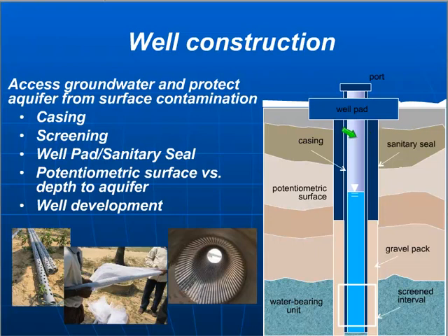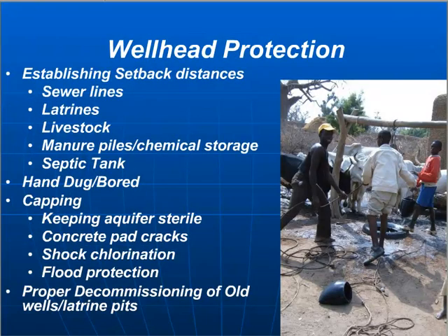And then one last slide on this borehole. There is a design that goes along with the well. Sometimes chapters say, oh no, we're going to install a well and we're using this driller, and that's all the information that's provided. But there is an actual design that you need where you specify the casing, the type of screen, the screening interval, specify that there'll be some sort of well pad, or what the sanitary seal is going to be, what's the space between the borehole and the well going to be to ensure that you don't have contaminants coming in from the surface and down into the water. And then the procedures for developing the well to ensure that it's clean. So there is a design involved with that well construction.